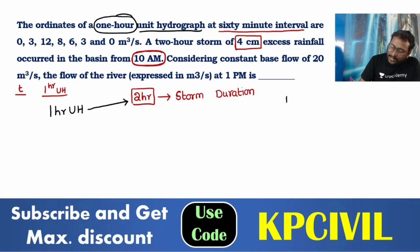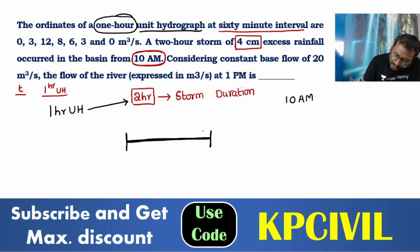Rain started at 10 a.m. So for that, I will convert this 0 to 2 hour storm into 2 storms: 0 to 1 hour storm, and 1 to 2 hour storm. Rainfall 1 for 1 hour, rainfall 2 for 1 hour.